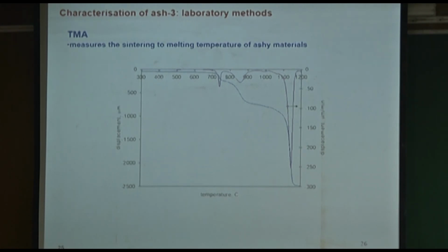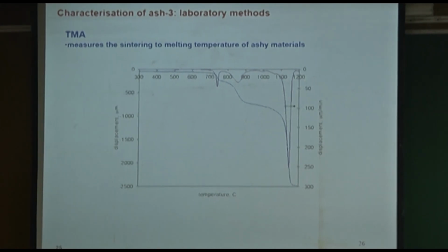You get the TGA signal and take the dW/dt, then you get the first derivative. The first derivative tells you where the transformations are taking place. It doesn't tell you what transformation is taking place, but it pinpoints where it is, whether it is large or sharp. And then, of course, you find it through the X-ray diffraction.